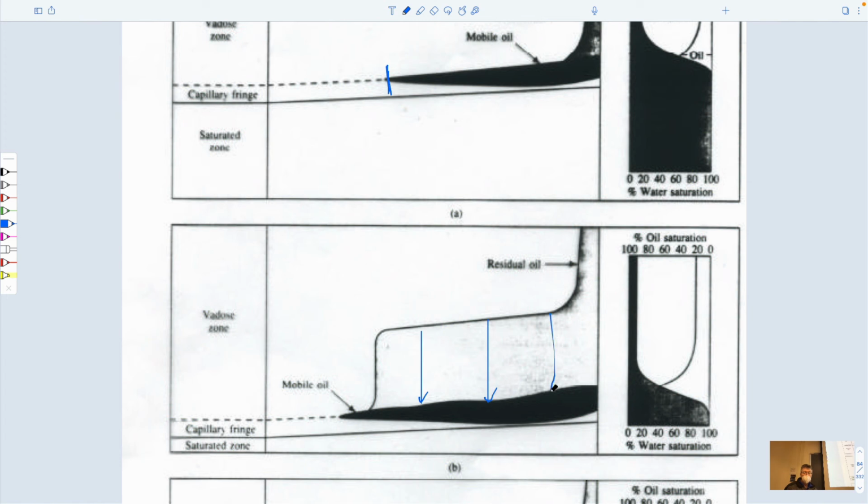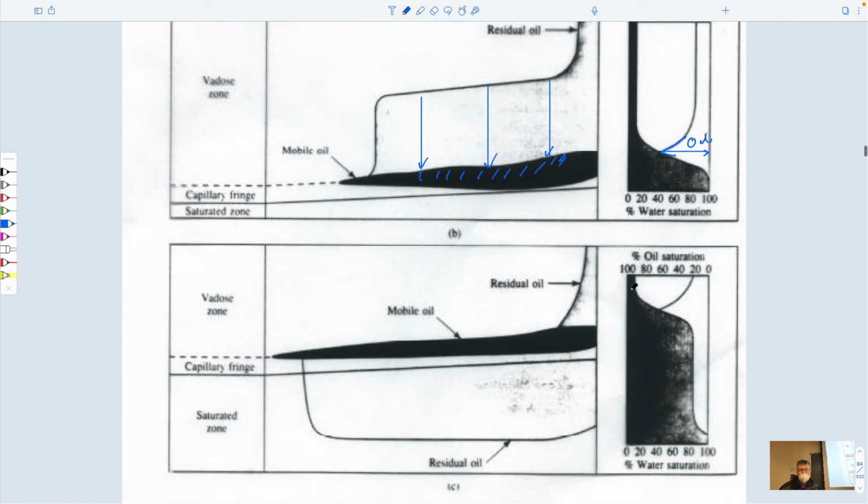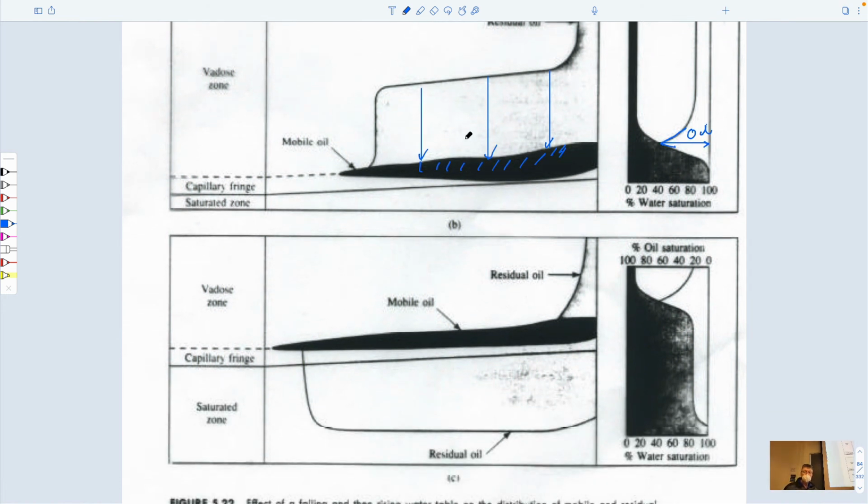And it will leave that there. And then in the wintertime, when recharge occurs, the profile, of course, would be to have the oil sitting. This would be an oil lens that's sitting on top, right? This is the kind of high saturation of oil that sits here, which is this lens, with water underneath it, which is the black. And then when the process is reversed, it shoots this buoyant layer up here as the water table rises. It plows it up like a snow plow in front of it, and you leave this residual.